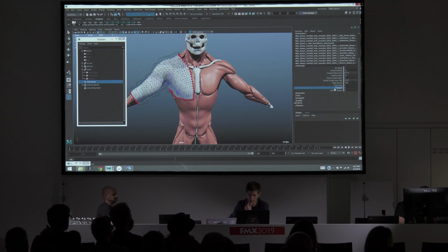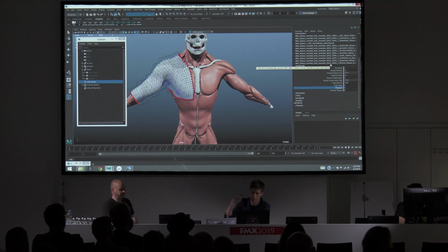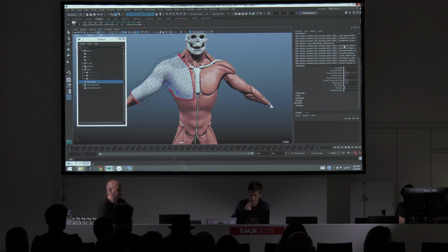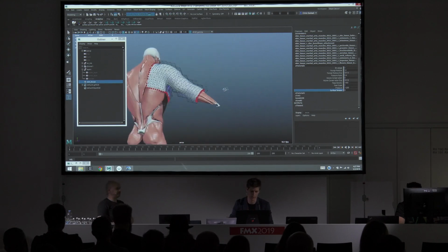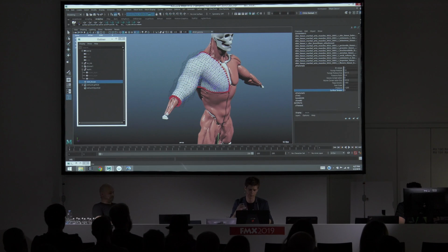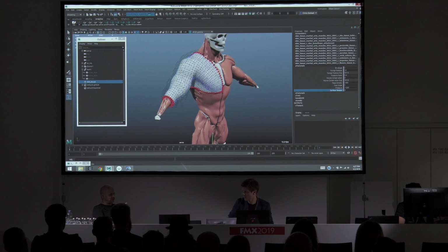You'll see that we have this pressure attribute in here. This is going to put a force in the normal direction, and effectively project the tissue down onto these underlying objects. So I could change this to, I think it's negative, I'll make it 1200 or something. And then we have the surface tension attribute as well, which is going to shrink the tets in the orthogonal direction to the normal of the surface. So it's going to shrink them anisotropically. That's right, isn't it? Yeah, it reduces the surface area of the surface triangles. Yep. And then I'll make that 20 or something.